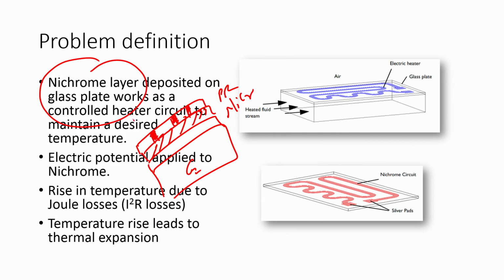After the mask, what can you do? You can expose with UV. After exposure, you have to perform the photoresist development. When you perform photoresist development, what do you get? You get photoresist on this particular area. This is your photoresist, this is your nichrome. Why do you have photoresist only in this area? Because your mask was a bright field mask, and the photoresist that we have considered is a positive photoresist. So, the area which is not exposed will get stronger.